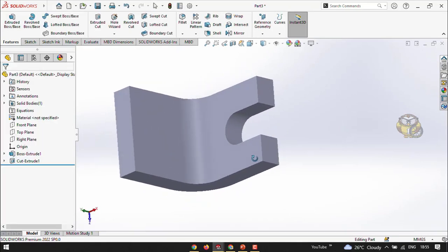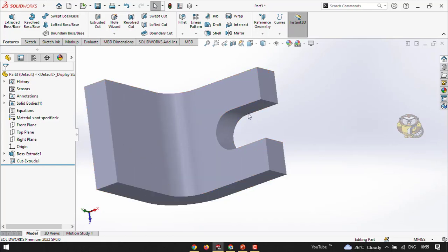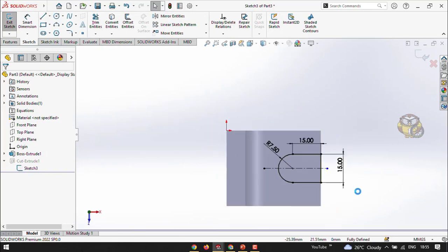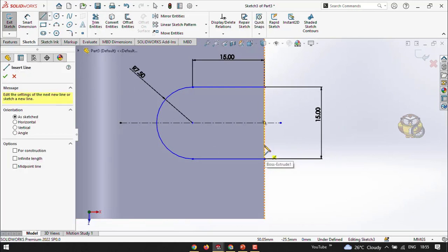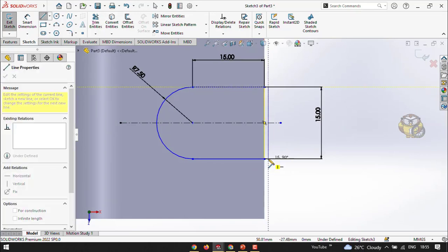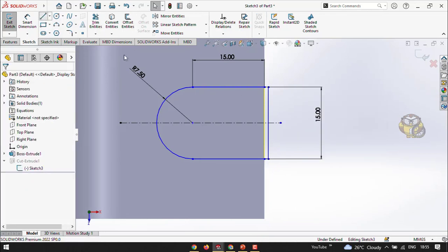See. Okay. As per my experience, most of them, it means 50% of students, make some mistake in this place. Where? Again I am going to create the sketch. See, most of the students forgot this edge. Here we have the edge. While you draw the rectangle or line, you should start from the edge. Some students start from outside like this, a little outside.